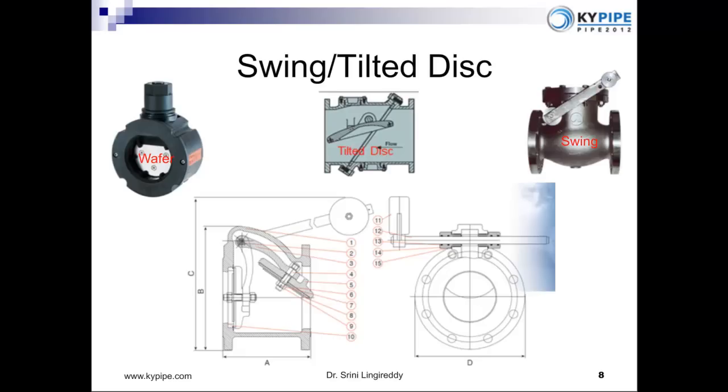When there is a flow or a pressure differential on the pump startup, the disc gets lifted up and stays in this position during the steady state flow, and when there is a pump trip and reverse flow, the disc starts closing, and it will close completely after some positive time, thereby preventing the reverse flow.